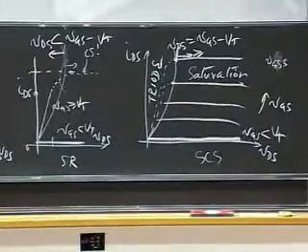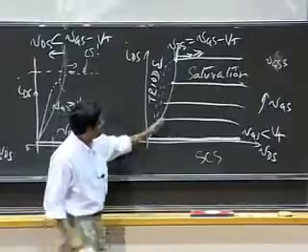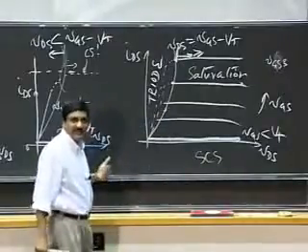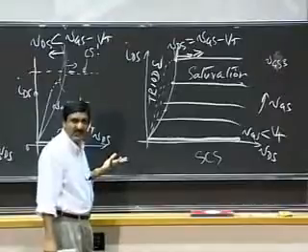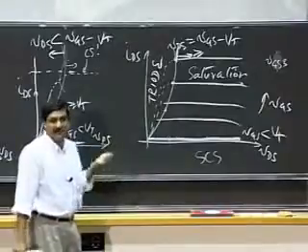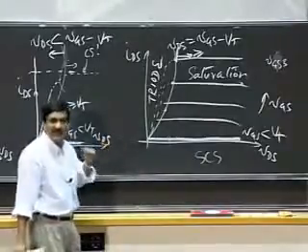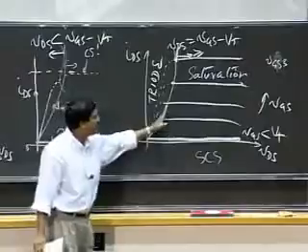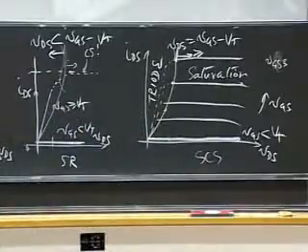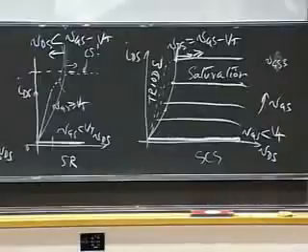Okay, this is really very simple. All we're doing is saying that when VDS is increased beyond a certain limit, given by VGS minus VT, the MOSFET begins to behave like a current source. It can't draw any more current. Okay, it limits the current to a given value, like a current source. But on the left-hand side of this, it behaves in a resistive manner.